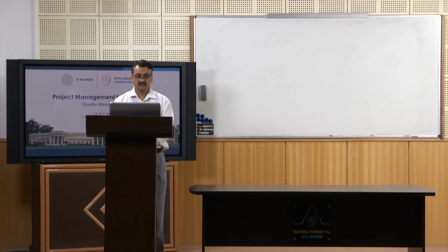So, if there is a product which consists of 100 parts and you assemble these 100 parts, you will get one final product, right. What is the probability that any specific unit of product is conforming? It would be 0.9973 to the power 100, right, isn't it?